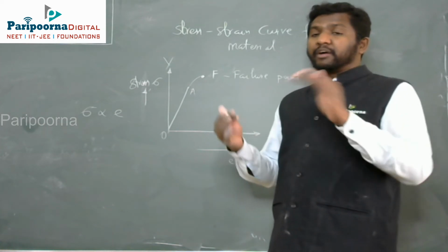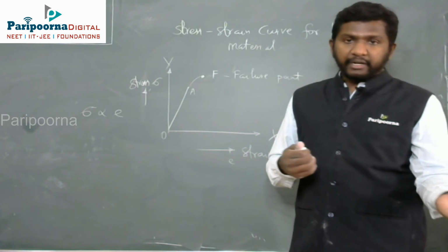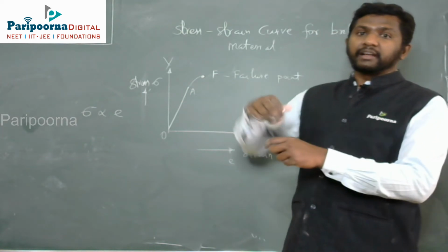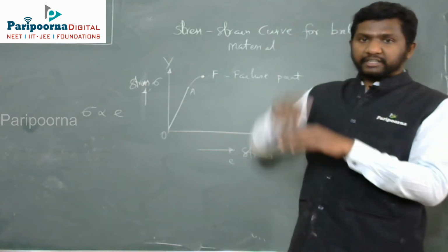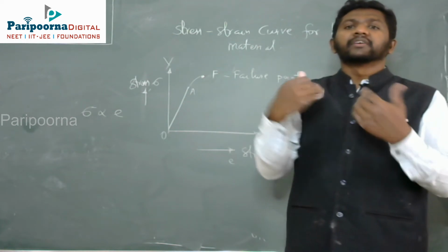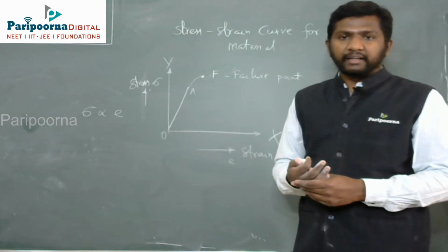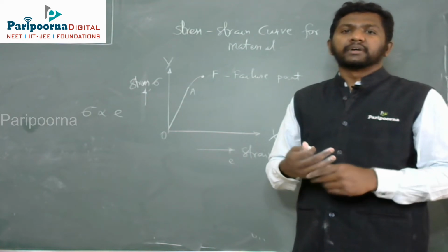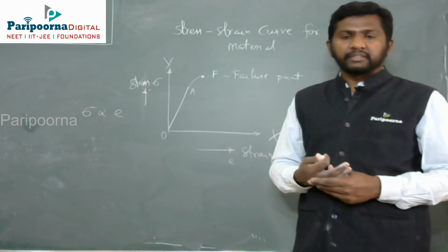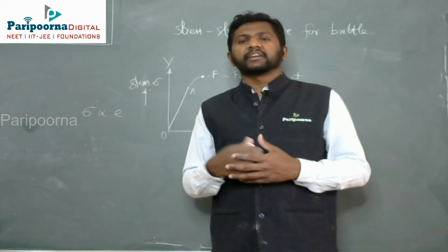Okay, you can compare the stress strain curve for elastic material, ductile material and brittle material. Okay, and you can identify the maximum strength of the material and where the failure occurs. Similarly, brittle material fails immediately, so we should not prefer brittle material. For ductile material, if you prefer it, the life of the engineering product will be longer. Like that you can understand and you can prepare.